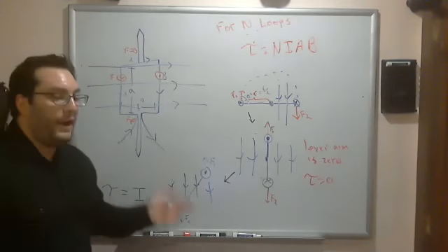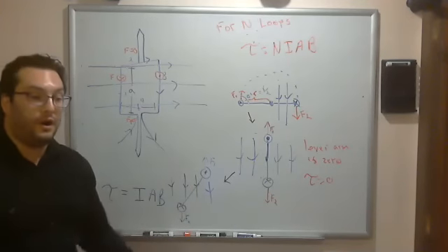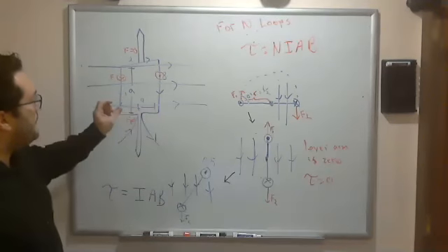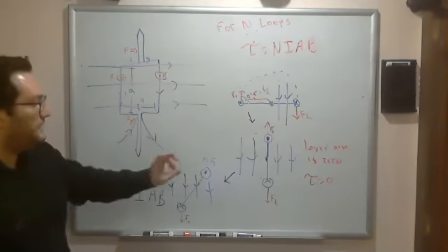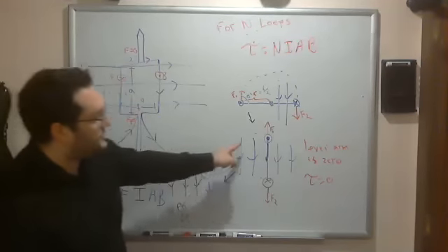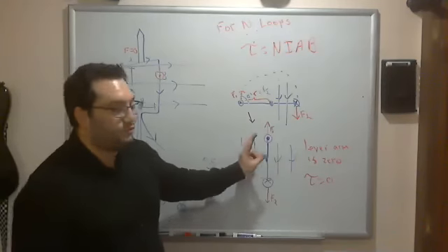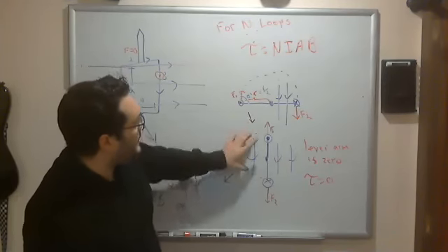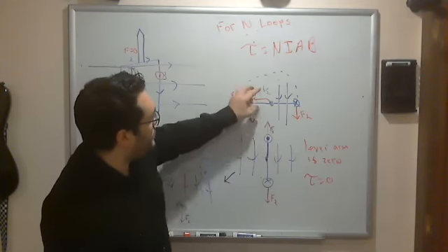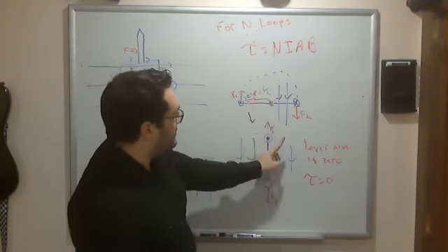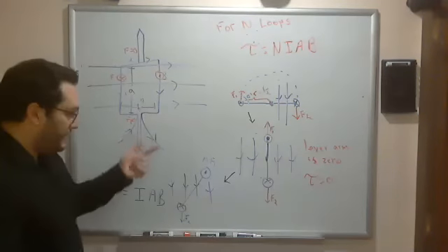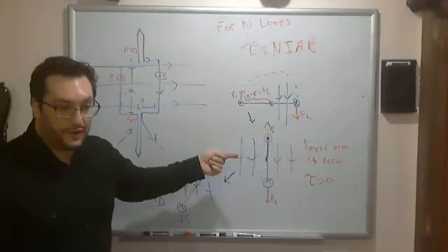And one way is to use an AC current that oscillates in sync or in phase with this rotation. So over here on this side, you would have a positive voltage when it's on this side, and then once it rotates and passes this point, the voltage will go negative. And then that would reverse the force, right?